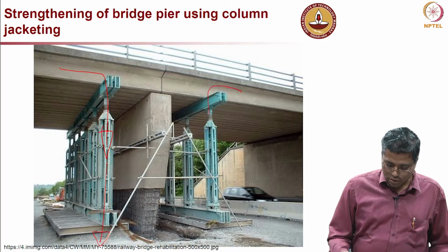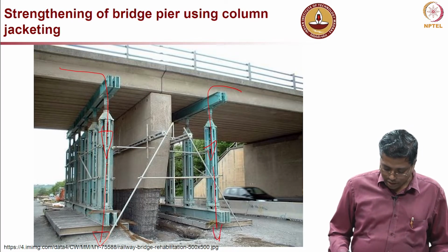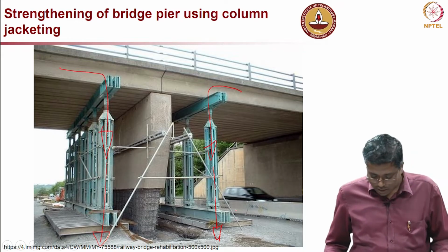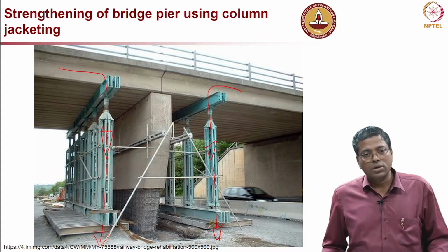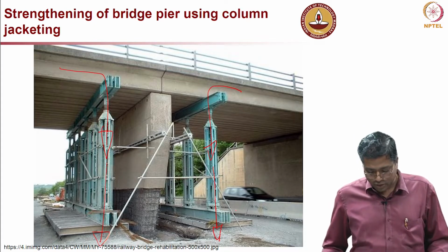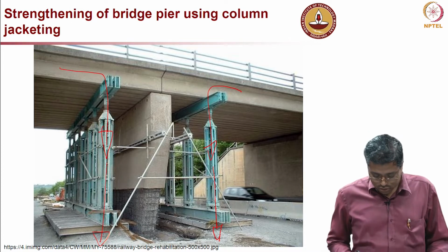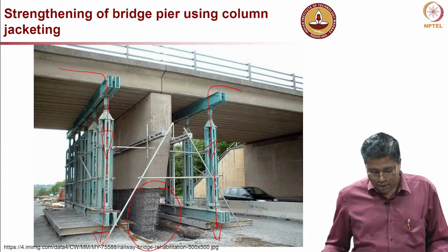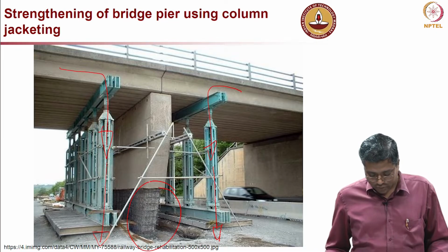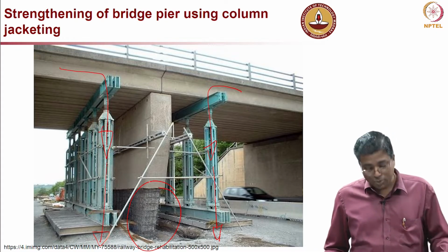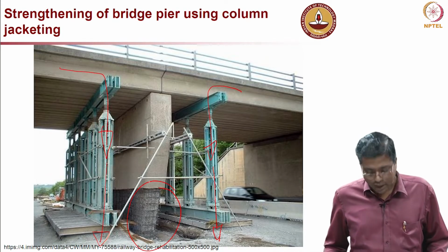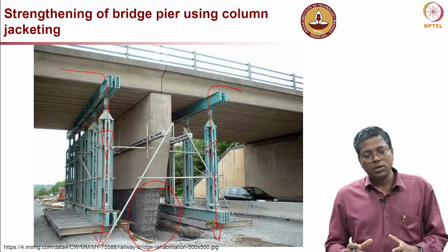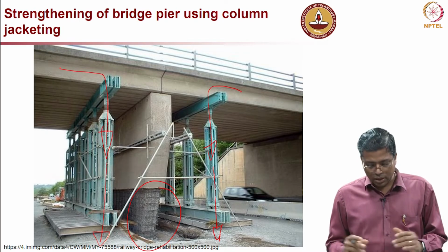Okay. So, here also you can see the load is directly taken and transferred to the ground by these props. These are heavy duty props. Depending on the type of structure, you have to decide what type of temporary support system needs to be used. And you can see here, this is the region which is going to be repaired. A significant amount of area has been removed from the concrete, from the pier, and when the new material is placed, it is supposed to share the load with the existing concrete.